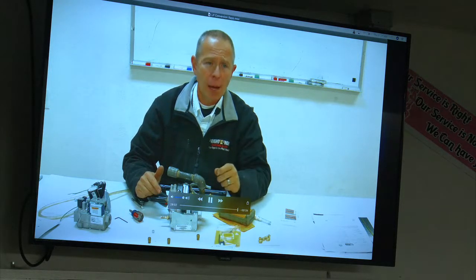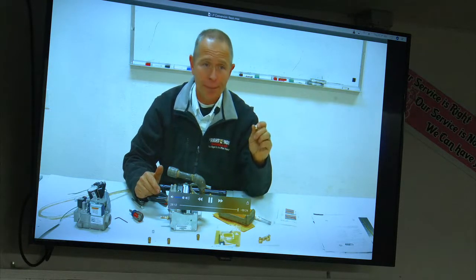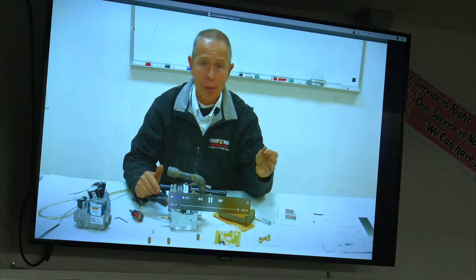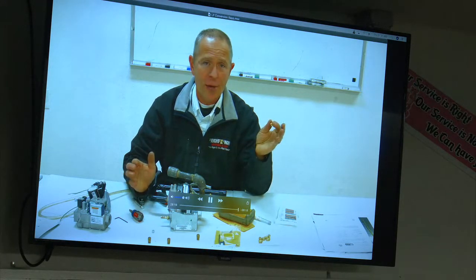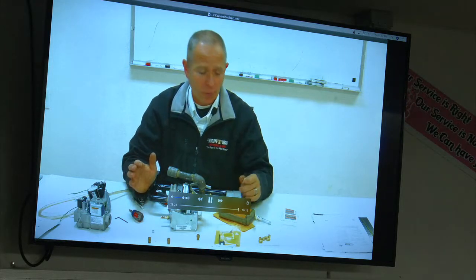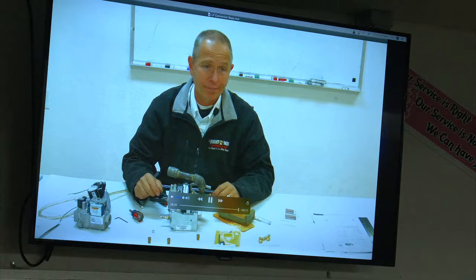Be a professional. If you don't have a manometer, get a manometer. Digital ones are nicer, because the yellow jackets, which I used for years and years, are fine until the first time you spring it, and then they're no good. So I use a water manometer. That's another way. I can zero it out, and it works in any elevation, but that's old school. So most everyone uses the digital, which is the proper way to adjust these.